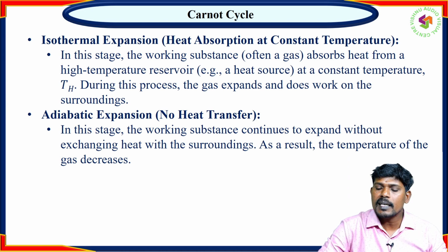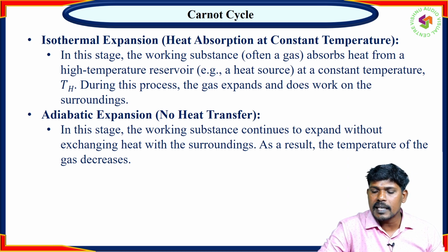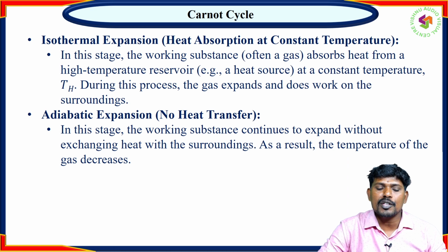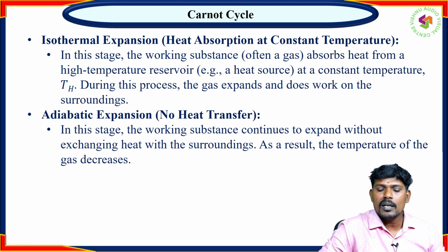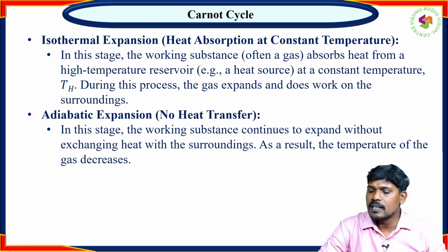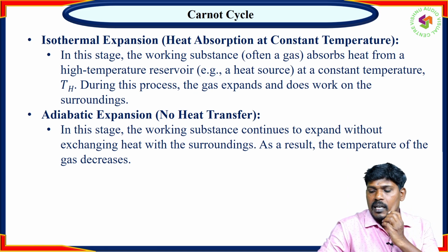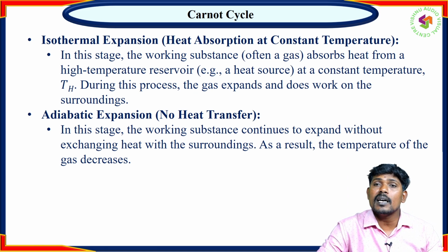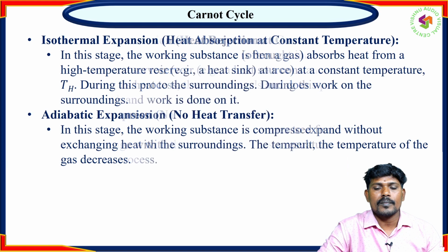Next, after the isothermal expansion, adiabatic expansion, where there is no heat loss. In this stage, the working substance, that is the gas, continues to expand without exchanging heat with the surroundings. As a result, the temperature of the gas decreases. So that means the heat is converted into work.